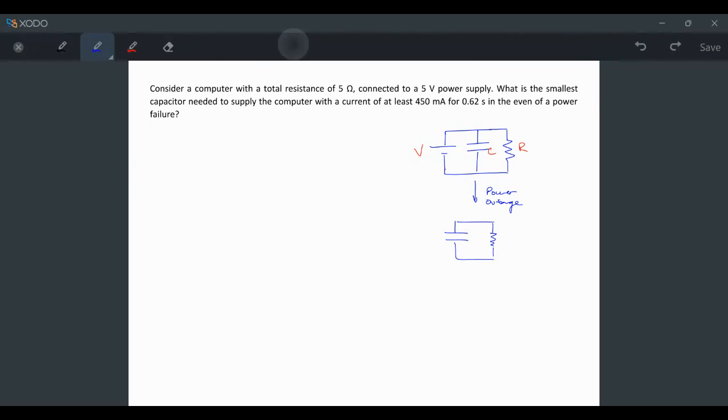this capacitor here, and we could go back and label it. Recall that when you have a battery or power supply, the big line of the symbol represents the positive terminal, and this represents the negative terminal. So this will charge up the capacitor. So this is positive and this is negative. What we will get is some sort of current, which will vary as a function of time, but it's going to flow through this resistor. And the current and the amount of time it can flow for, the decay envelope that we expect, is going to depend on what the capacitance is and what the resistance is.